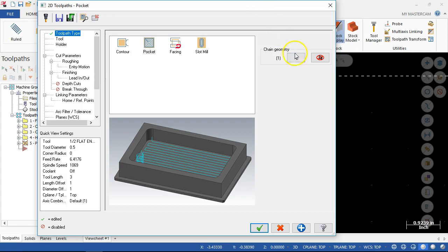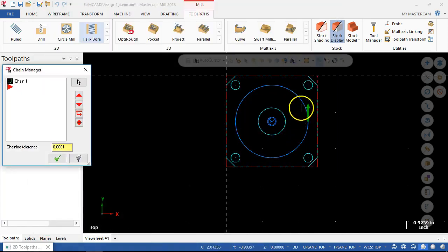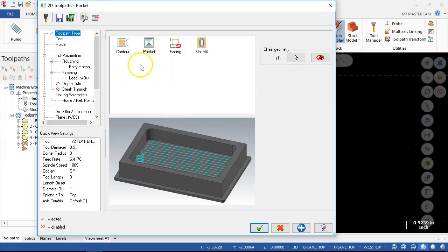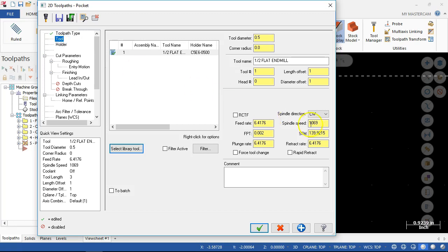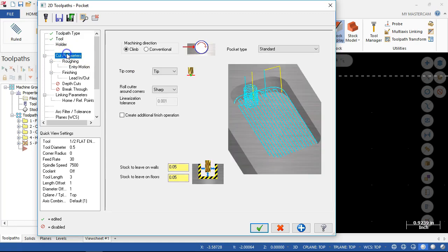And so, now let's get back in that. So as the tool's spinning and coming around the pocket this way, that is staying in climb. All right, 1/2 inch tool, and because we changed operations, I really didn't expect that one. All right, I'm not going to worry about the rapids, but get in the habit of observing those numbers and putting in hopefully realistic cutting speeds and feeds.